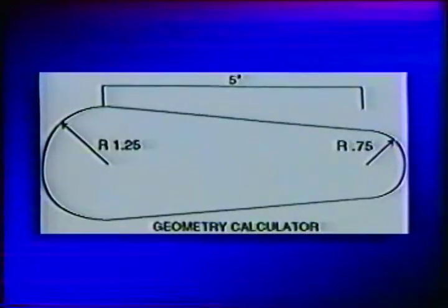The left-hand column of icons is used for inputting points onto the screen. The center column is used for inputting lines. The column on the right is for inputting circles, with the exception of the last two definitions, which are used to input lines tangent to circles. I'll give you an example of an oblong slot.